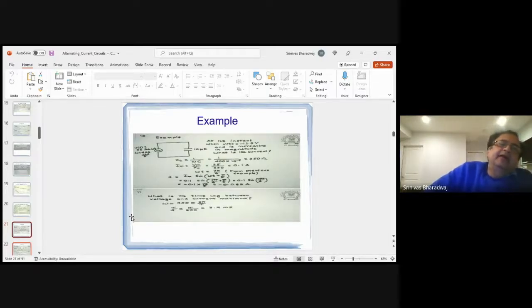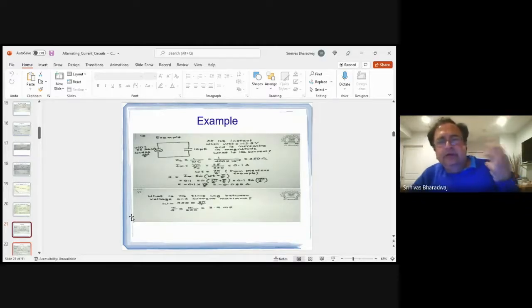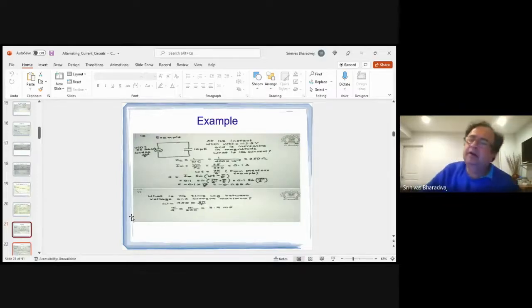So you treat impedance as the real part resistance plus j times the imaginary part reactance. Okay, so understand the dynamic behind that. So why is there this omega there? This omega is there because you're taking a derivative. Therefore that's how you end up with that c dV by dt.